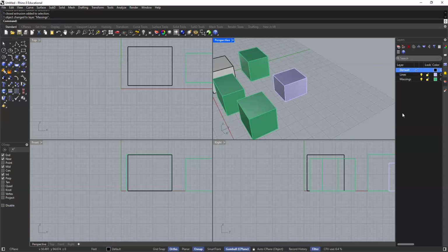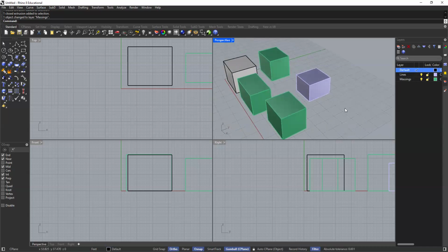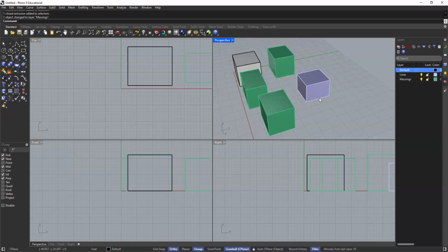I prefer to always work in the default layer simply because when I'm modeling, I'm very invested and focused on what it is I'm modeling, and I forget all about changing the layers before I start modeling, say, my walls, and then I'll get into the windows and I'll forget to change my layer to the Windows layer and so on, right?